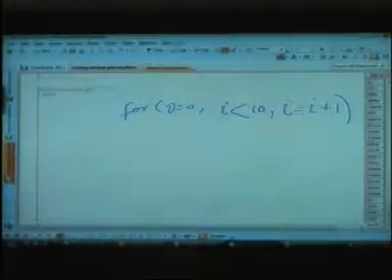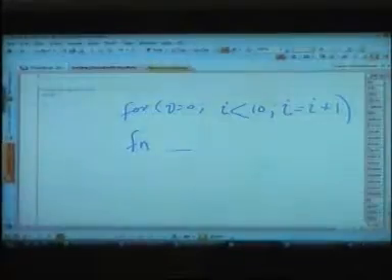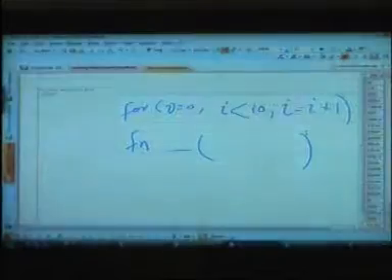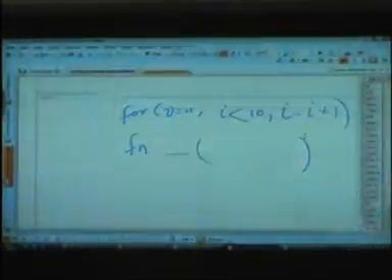If there is a function, so you define a function in Verilog, any function. As in C, function means something very different: a common code you write at one place so that whenever you intend to call it, your program flow goes there, executes it and comes back. But in Verilog, function means hardware. If you are calling it 10 times, it means the hardware gets replicated 10 times. Writing a function does not mean that it is done once, and every time the hardware requires that function to be executed, it goes there, executes it and comes back. No, it does not happen like this in Verilog, and that's what I am emphasizing.